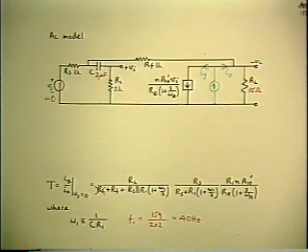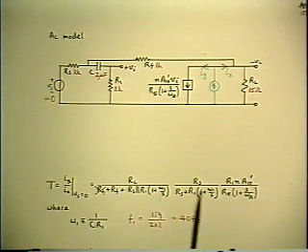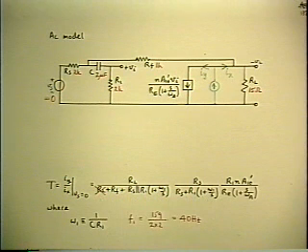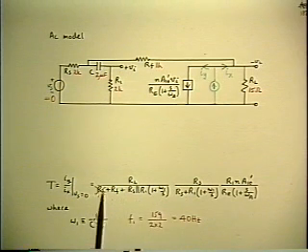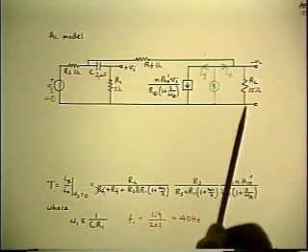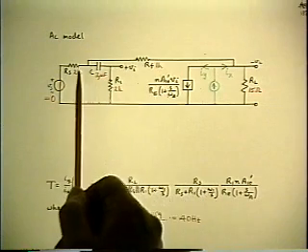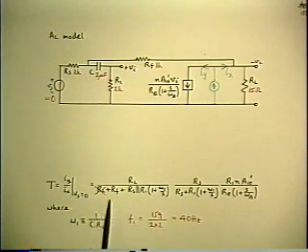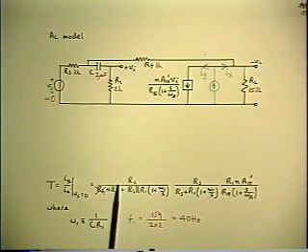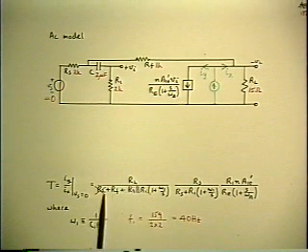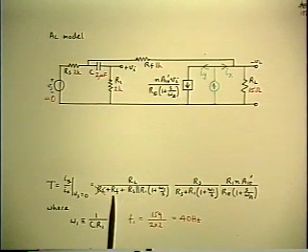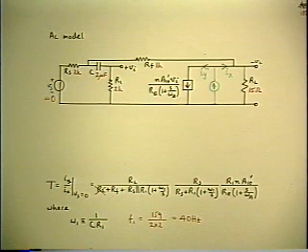But it isn't in fact at pole zero form, because this corner frequency is buried in a couple of series parallel combinations. Also, notice I've dropped the RL because it's negligible compared to the RF. So there's using numerical values to justify an analytic approximation, because I'm leaving the rest of it in symbols.